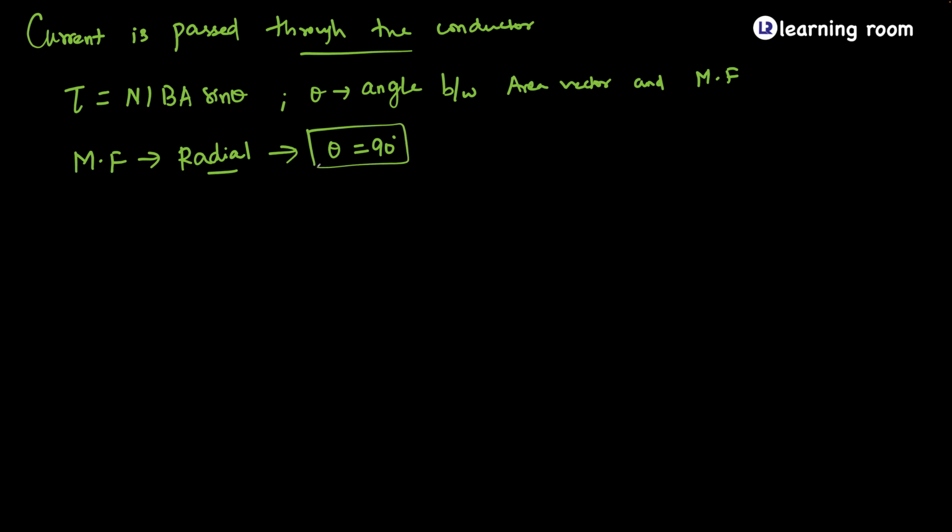Okay, the reason why we are actually generating magnetic field is we want to ensure that the torque experienced by the current carrying coil is always maximum. So who decides the maximum value here? The number of turns inside the coil is fixed. I is dependent on how much current you are passing from the external source. Magnetic field is decided by the concave shaped magnets that you use. Area of the coil is decided by the length of the soft iron core across which you are going to wind. So who is the only parameter that can actually control and make the torque be maximum?